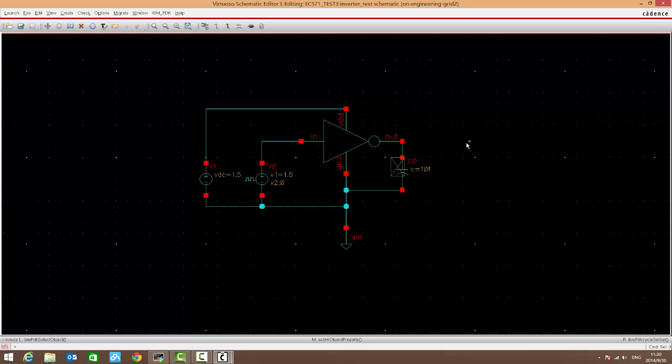So, this is the symbol we drew, and it occupies the area of this big box. And we can't put our components too close to it, so it overlaps. Let's move this here. Delete the wire and reconnect it to this one, to ground. Check and save. Okay. Now we have finished more like a test bench of the inverter.